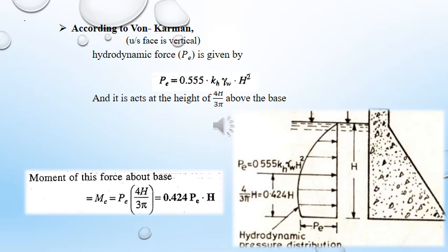So, a horizontal acceleration towards the reservoir causes a momentary increase in water pressure as the foundation and dam accelerate towards the reservoir, and the water resists the movement due to its inertia. Thus the force is taken as acting in the opposite direction of the earthquake acceleration, and similar pressure will be developed on the downstream tailwater when the earthquake is reversed.